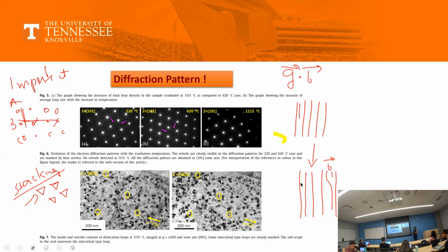Okay. So for the people who will do yields, number one thing, even if you are not doing yields for the technical analysis, you are doing yields to measure the thickness of the sample, all of you. And why is the thickness of my sample so important? For example, if you were seeing the voids, or tomorrow you go to a lab and you start scanning your sample in 5D, and you tell me, hey Shradha, is the sample good? What I will tell you is, how thick is it? That would be my number one question.